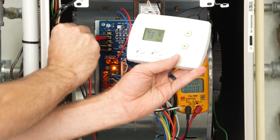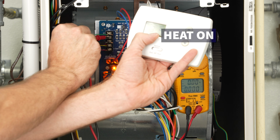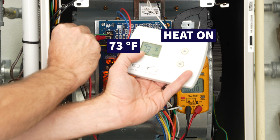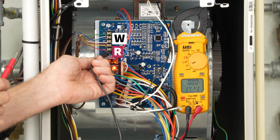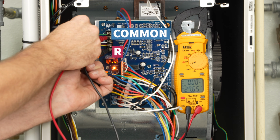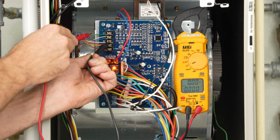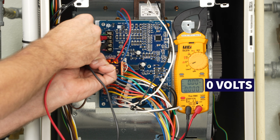So the heat should be running right now if we have this set at, say, 76, and it says heat on, and 73 degrees is what it is in the building. It's obviously not connecting the R and the W inside the thermostat. Now, between R and common, you can see you have 27 volts. So if R and W were touching in the thermostat, then we would have a 24 volt signal on the W, and you see right now we don't.